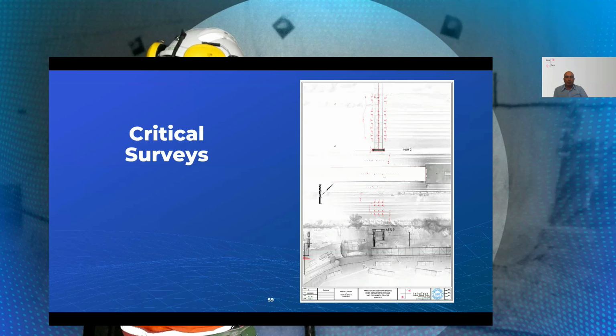We went back to make sure that everything is okay, that this bridge is going to fit, and we scanned the bridge itself, and this is one scan that you see all at once. On the upper side, you see a lower intensity because we shot it from far away. And the more intensity, the darker intensity, that means we were closer to our target. Nevertheless, even the points with less intensity, it's so much more information available that we still can work with that.